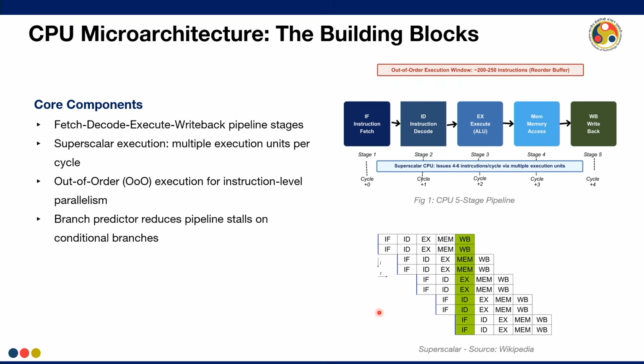All the modern processors are basically superscalar engines. There are no scalar engines doing only a single pipeline; rather they have a lot of pipelines. That means there will be 4 to 6 instructions issued at the same time, and they will go through these pipeline stages subsequently.